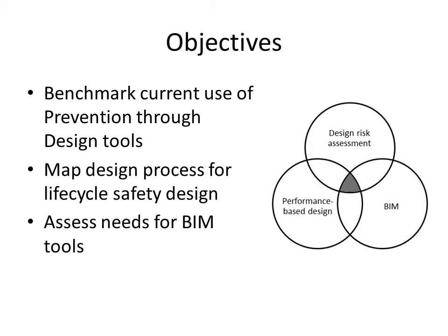Under the UK CDM approved code of practice, the process of design risk management is concerned with health and safety in construction as an integral part of the design process. Design risk assessment is defined as the process of design risk management, which involves identifying hazards or hazardous activities and any associated risks relating to the intended construction work, which includes building structures, maintaining, cleaning, using in certain circumstances, and removing them.